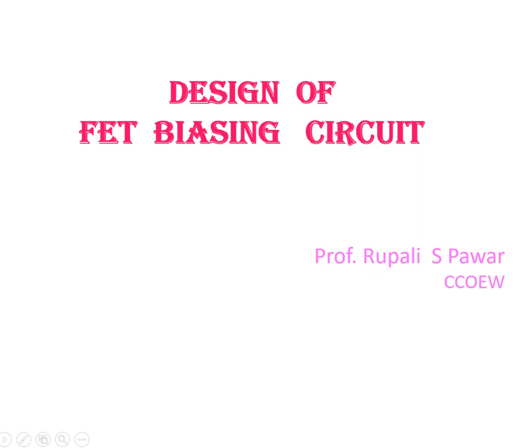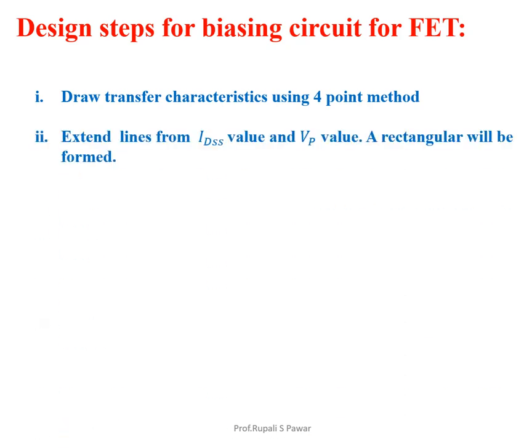Welcome. Let us learn design of FET biasing circuit. Here are the designing steps. Step 1. Draw transfer characteristics using 4-point method. Step 2. Extend lines from IDSS value and IP value. A rectangle will be formed.